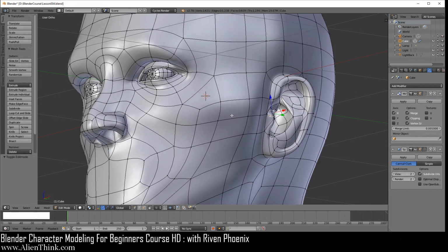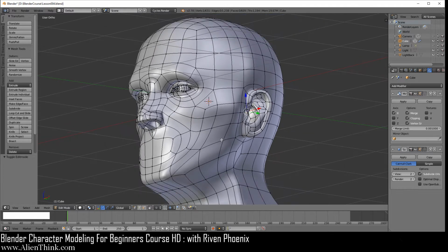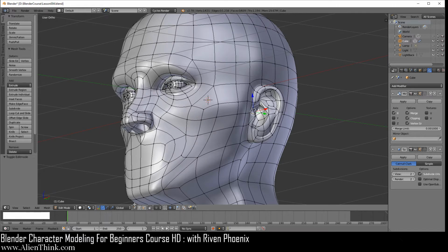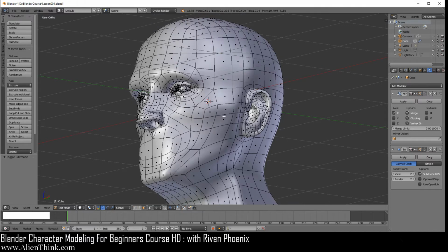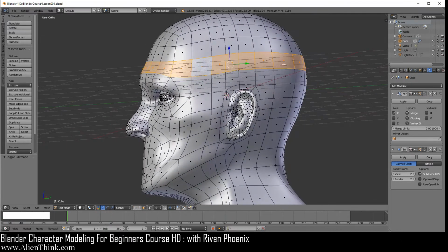One of the key concepts with quads is that not only do they allow you to model your design very quickly with the subdivision modifier over here, but what quads also allow you to do, as you've seen, is select these edge loops, so we can determine how these quads are actually traveling around the human head. If I do Alt and click on this, you can see that I can very quickly select this entire edge loop.